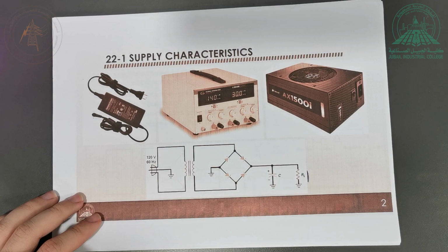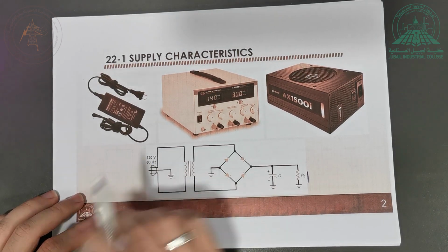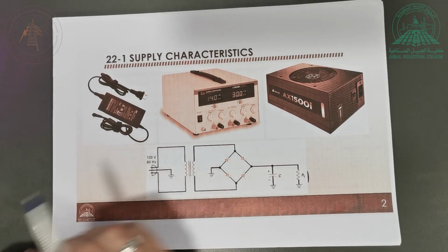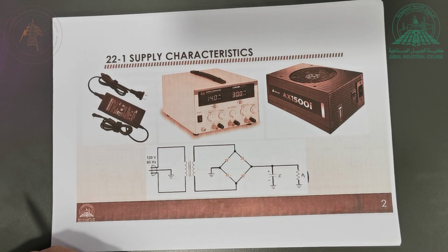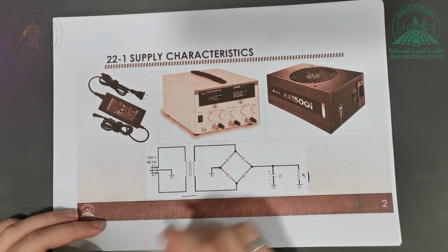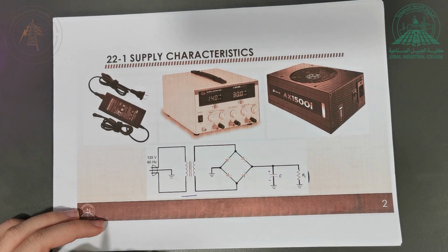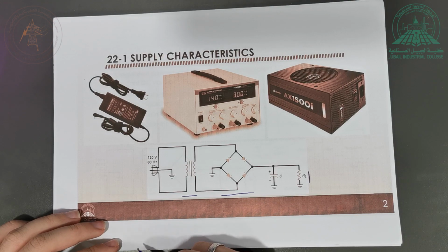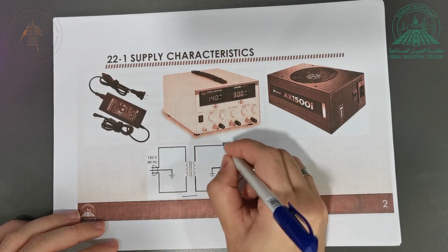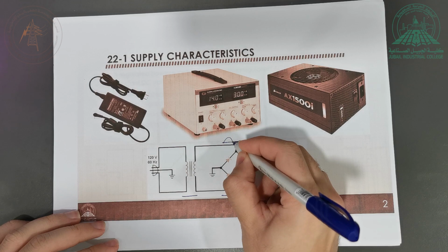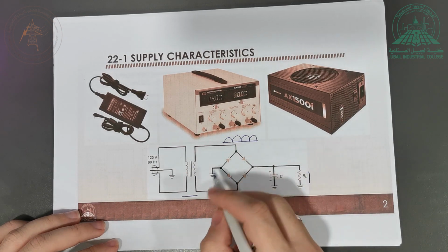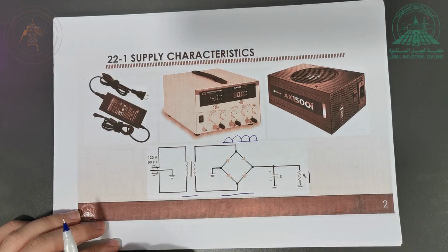The laptop, of course, is not going to take an AC voltage, and it's not going to take a high voltage like 120 volts, as in this case. So what do we do? The first step, we step down the voltage by this step down transformer, as you have seen in the lab. Then right here we have the full wave bridge rectifier, right? Remember that right here the signal is going to look like this, right? The full wave bridge rectifier is going to make everything positive, so pass the positive, and the negative part of the signal is going also to make it positive.